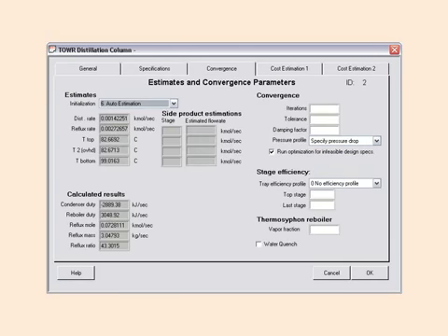After running the tower model, we can double click on the column icon and click on the Conversions tab to get the information found in the ChemCAD simulation using this new tower model. We can determine the condenser and reboiler duty. In this case, we have a condenser duty of minus 2889 kilojoules per second, reboiler duty of 3048 kilowatts.